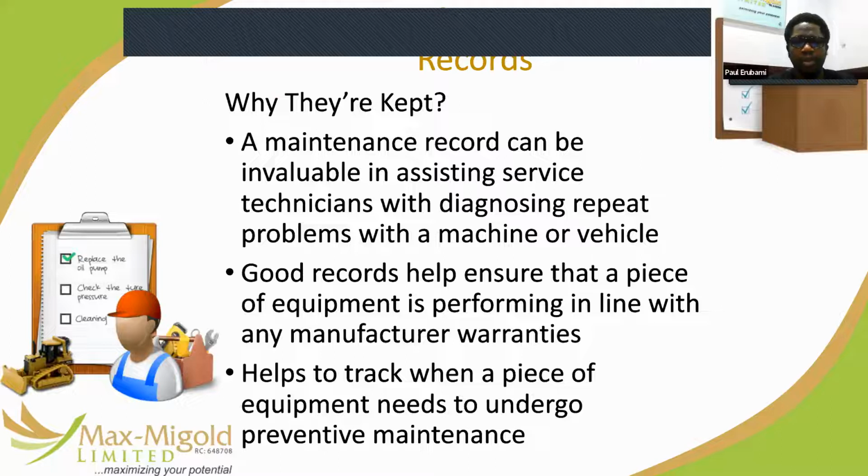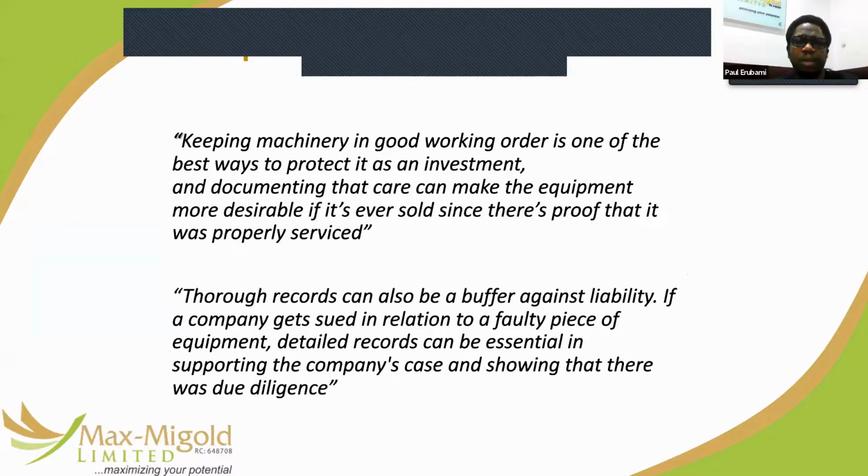It's a huge asset to have proper maintenance records, because people servicing an asset, maintaining an asset, repairing an asset, get to know what happened before. They get a sense of the history, the problems they had before. It's easier to judge a problem that you're experiencing now because you've seen the history, okay? And then track when it needs to undergo maintenance, especially when you're trying to schedule frequencies for certain maintenance activities. Sometimes you may need to do something quicker than before because you've looked at the history, and if you keep it longer, it will become problematic.